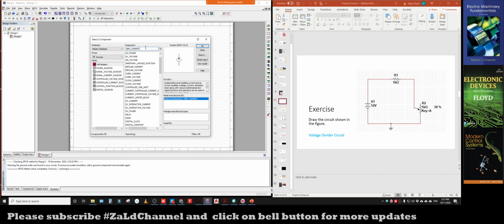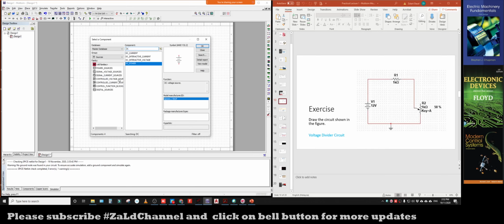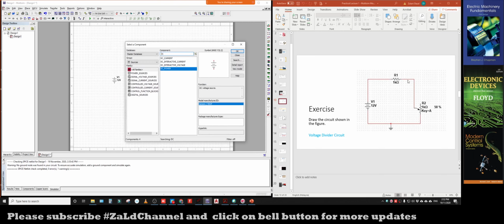So another tip that you can follow is, if you know that you want to place the DC source, just type the DC source. Let's say I type DC here at the component search bar. At the component search area, 4 types of DC source will appear, which are DC current, DC interactive current, DC interactive voltage, DC power. So what we are going to place is the DC power source, which is something that looks like this, the 12 volt like this, right? So by default, click on this and then left click to place the component. After you left click and place the component, the library appears again, meaning that it asks you to place another component. Okay, so next we want to place the resistor component.